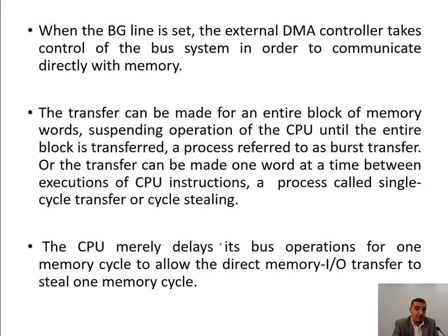The transfer can be made for an entire block of words, suspending the operation of the CPU until the entire block is transferred, a process referred to as burst transfer or chunk transfer. The CPU merely delays the bus operations for one memory cycle to allow direct memory input-output transfer for one cycle.